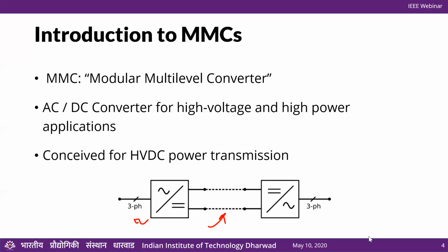Okay. So what I was talking about is this converter scheme where you have three-phase AC coming in here, and then that's converted to a DC link, and then the DC link is converted back into an AC. And this is where HVDC MMCs really found a lot of favor. Now, of course, we've gone beyond HVDC applications. Now they're applied to industrial drives. They're now finding favor in renewables, especially in wind energy, where converters that have a small footprint are desirable, and so a lot of benefits are there in all these newer applications.